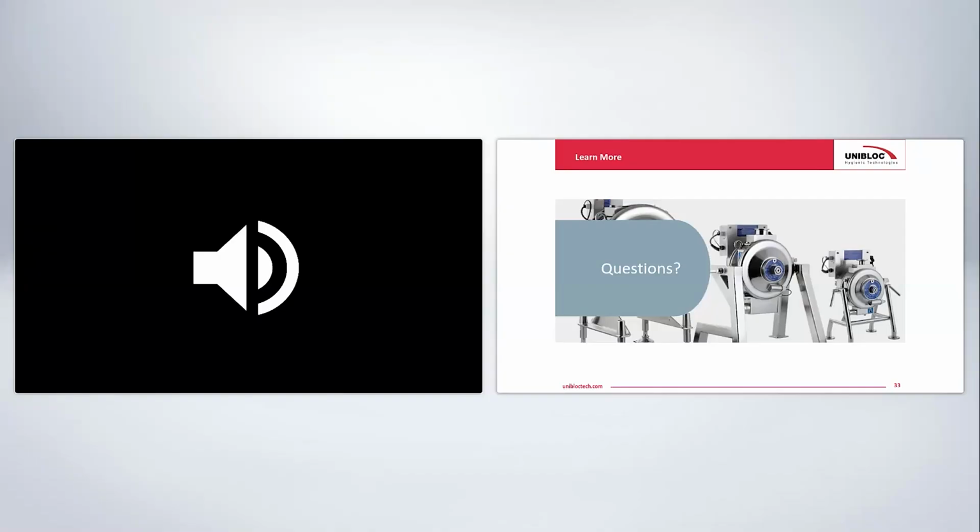Sounds good. The next question is, what instrumentation is recommended for AODDs? For instrumentation, it's always good to have any extra equipment for the pump. A pressure gauge. You need to know how much air you're supplying to the pump. And then we talked briefly about having clean, dry air. So you're going to want a filter regulator for the pump so you can control the pressure and the volume of the air going to it. But they are fairly straightforward. You just have to connect that air to the air valve, and then they're good to go. So not much instrumentation is needed.